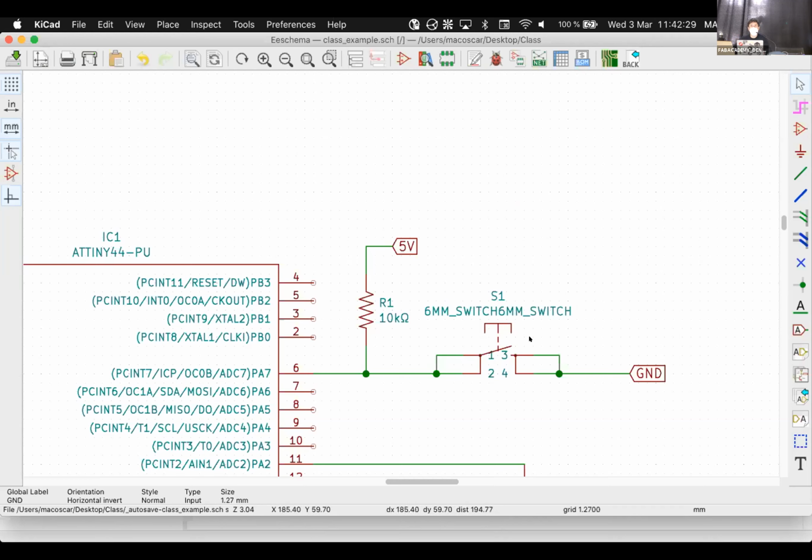The current that you're going to have is in combination of this resistor here and the resistor that you have inside the microcontroller, that's the resistor that you activate when you say pin mode input. You activate that resistor, physically, plus this resistor here. The combination is so high that the current is going to be of the order of nanoamps, maybe. There's some current, but it's very low. It's some consumption that you have there, but it's so tiny that it's negligible.